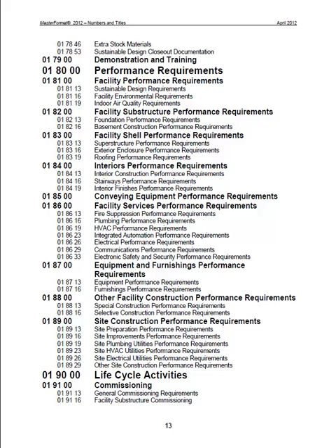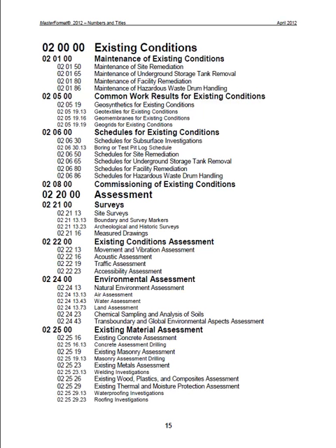What happens is, instead of pushing air through, it's drawing air out and working against some other thing, and all of a sudden you're saying, geez, this room's hot, or this room's cold, and everything else seems fine. What's going on? You find out somebody just wired up a fan backwards. And then we have decommissioning, kind of the reverse.